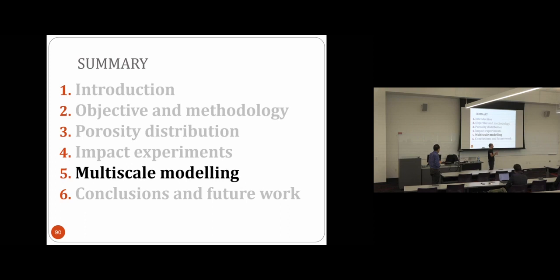In experiments like the ring fragmentation or the tube fragmentation, it is almost impossible because the thing is flying. But at least we can track the radial velocity with the PDV system, and this allows us to obtain the strain rate, so it's not bad. I mean, it's not easy. The instrumentation of these experiments sometimes is not really easy. But we have some quantitative data, very useful for modelers.